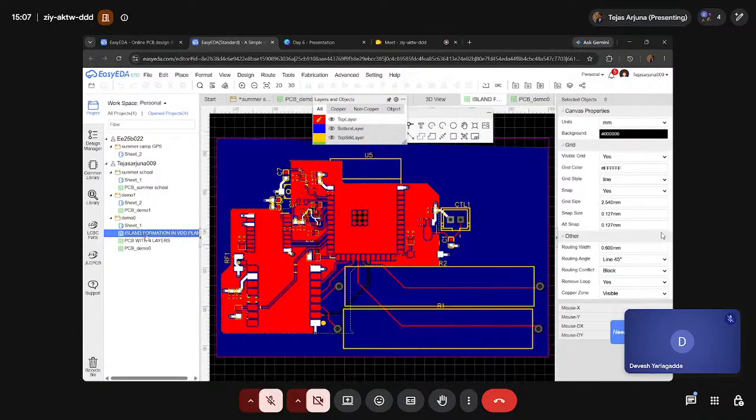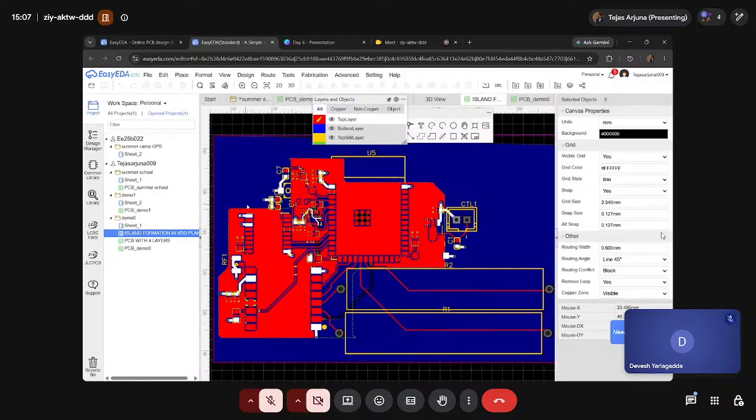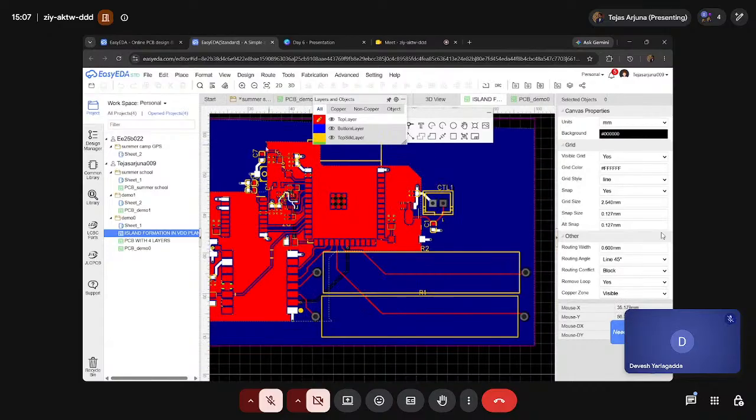But sometimes, if I had made the VDD plane like this instead of getting cut over here itself, this would have gone till here and the connection would have gone. But the problem is, if you do that, it would be fine, but the copper area length, the length of the loop will increase. That is the reason we use 4 layers.